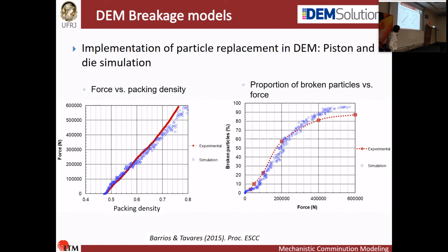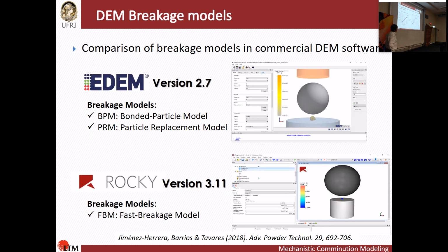You can see here, on the basis of testing single particles, when we simulated the bed, we got some quite reasonable predictions. Here the red line is the experiment, that is the force that you apply and the packing density, how much of the material is being squeezed, and actually pretty good predictions here with the simulation. And if you even further count the number of particles that broke as you increase the force, actually the fit was pretty good. So the model is giving a reasonable representation of something which is still a simple size reduction system. And this is all done in DEM.